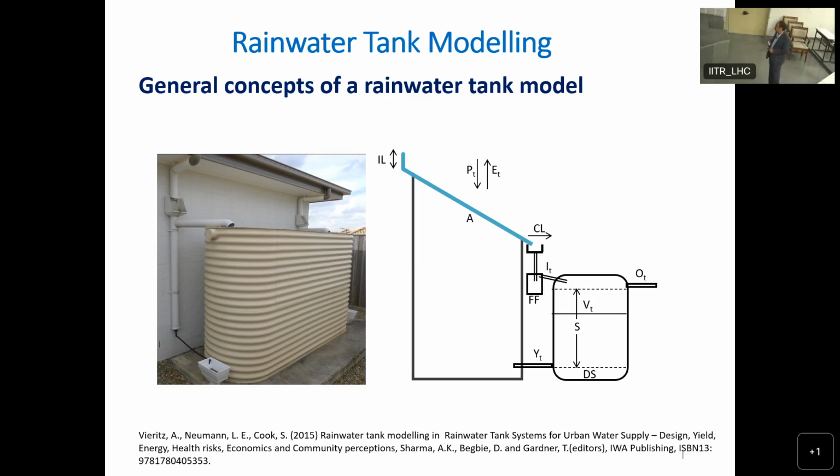And then the water going down. And this is the dry volume where all the sedimentation will be deposited, and then you can clean it periodically. That's why this gap: the outflow is slightly above the bottom of the tank. You can periodically clean it and remove the sedimentation from here.